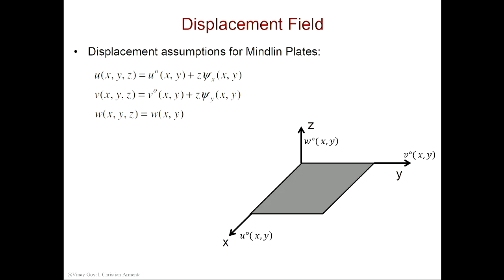So for example, if somebody took, I don't know why anybody would do that, but took this table, put it against that wall, and pushed against that wall, that's the in-plane direction. If you put weight onto this, that's the out-of-plane direction. Okay, it's perpendicular to the plane of that mid-surface. So this is called out of plane. And these two right here are called in plane. These are the in-plane directions of the plate.